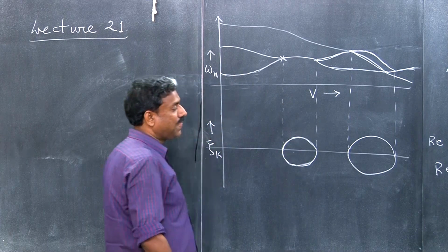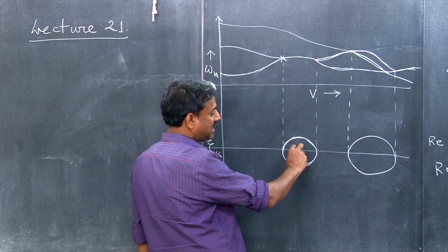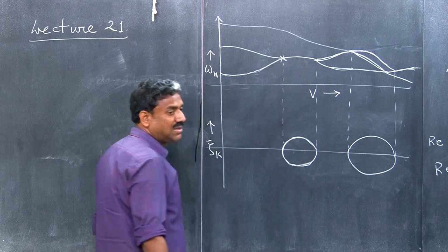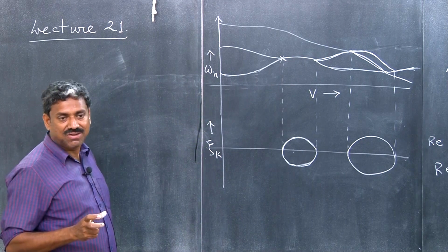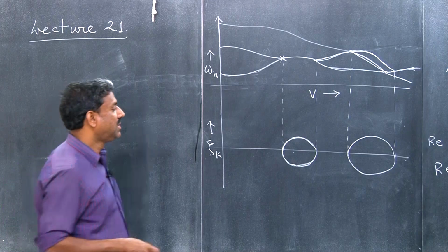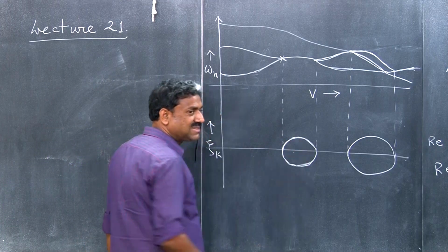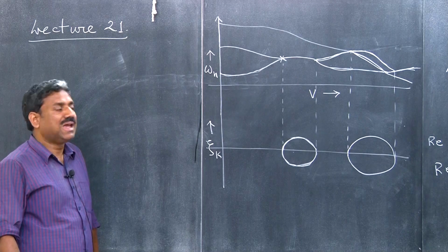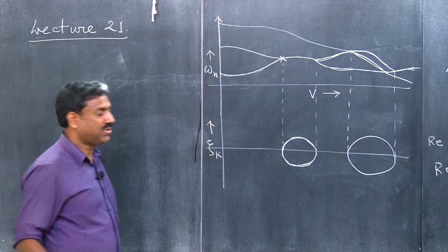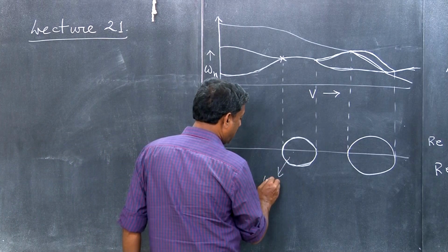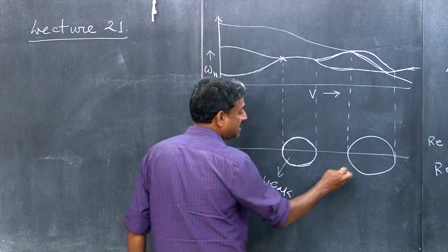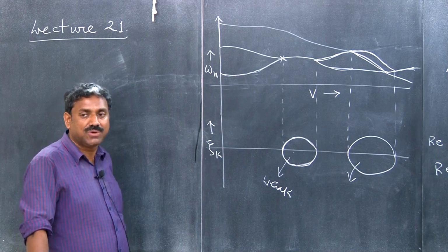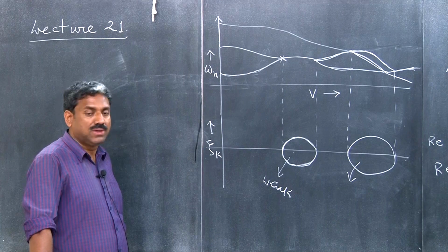So this indicates these are the flutter regime, you see that, okay. And you see that sometimes the weight for the coalescing zone can be very small. The smaller it is, the smaller is the strength of that instability, and these are called weak flutter and strong flutter. Weak flutter can be suppressed by increasing the damping in the system, whereas strong flutter may not be, okay.